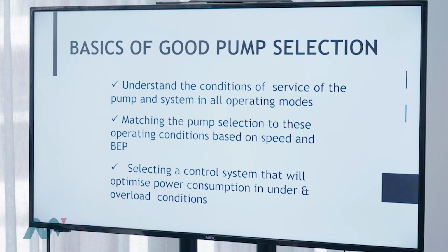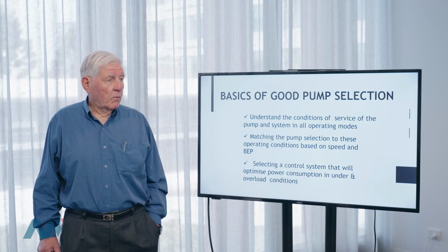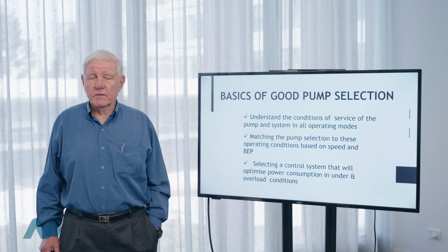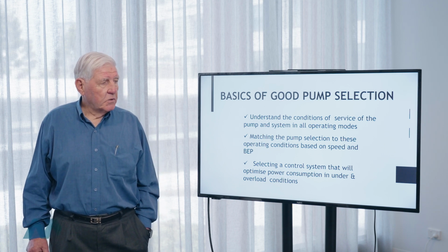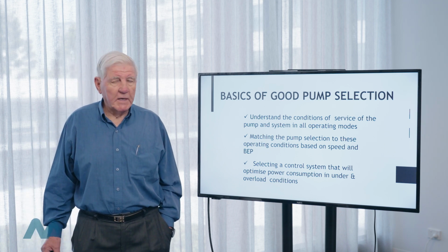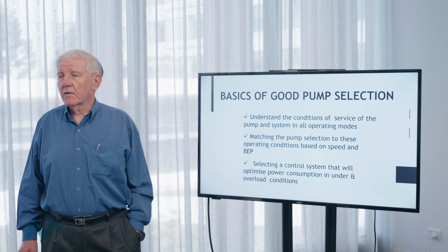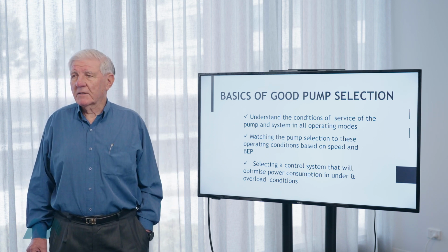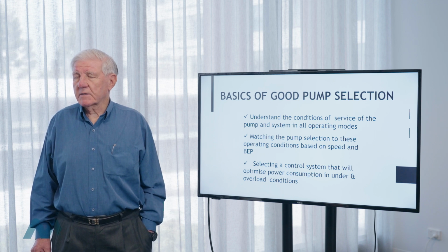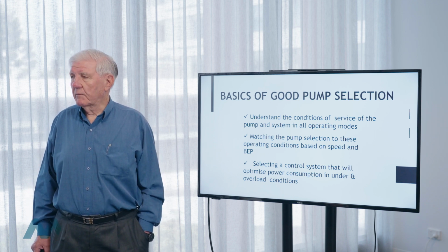The most important factor in making a good pump selection is actually knowing the conditions of service that the pump needs to cope with. Once you've got that information from your customer, you need to match the pump selection to those operating conditions based on the speed of rotation that the client might nominate, and also try to make the duty point as close to BEP of the pump curve as you can.